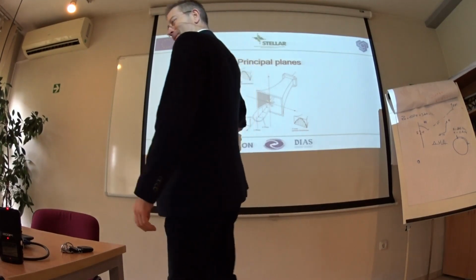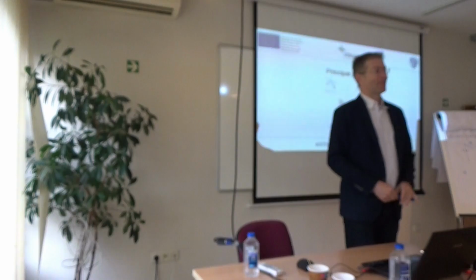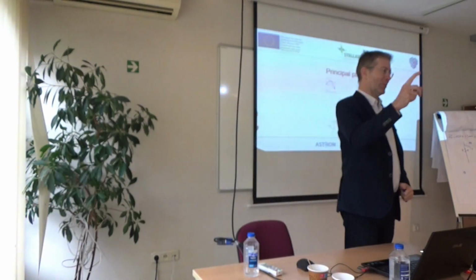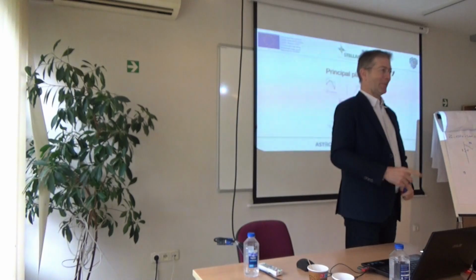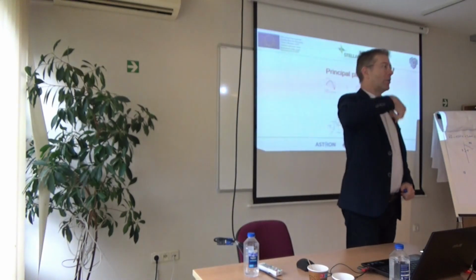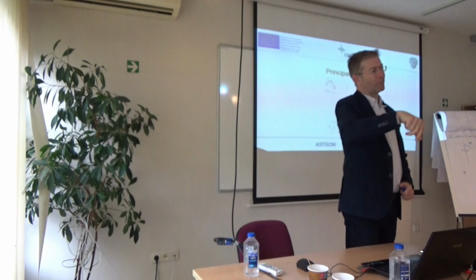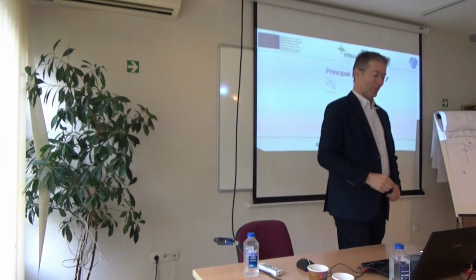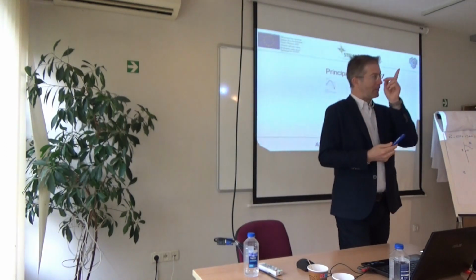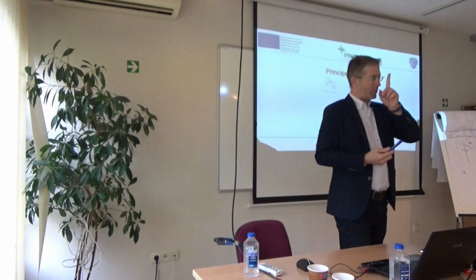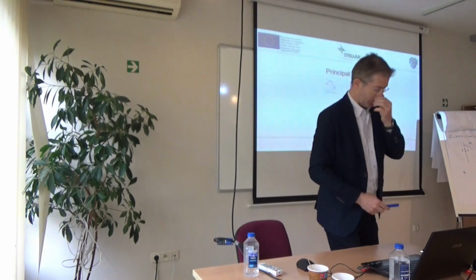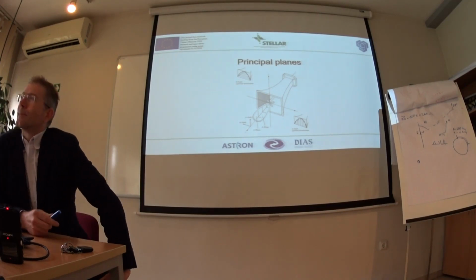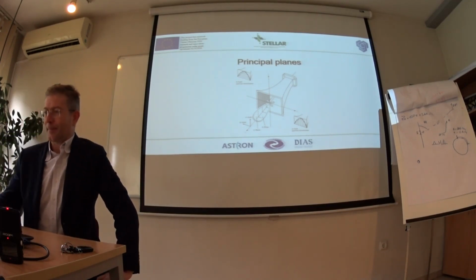Maybe the moon is not a good example because it's always facing with the same side. It's easy to know what is what, yes. But if we fly a spacecraft, on each circle it transmits in a different polarization. Yeah. So we have to run the numbers every time and align the antenna polarization with the polarization of the source. Very good.